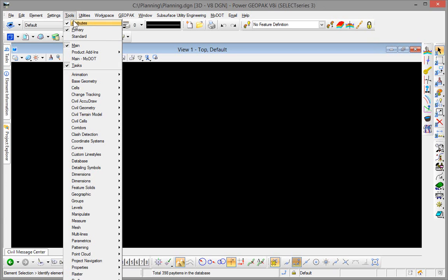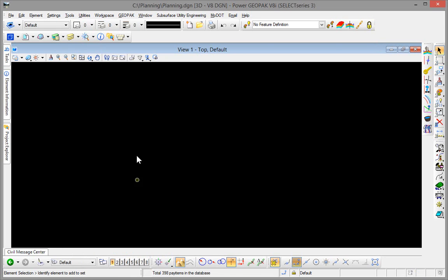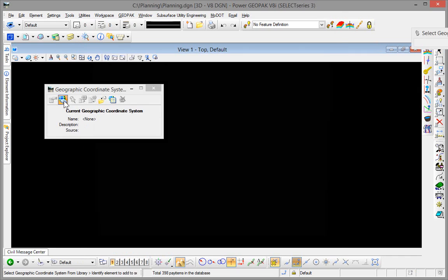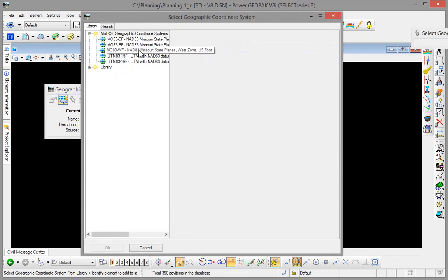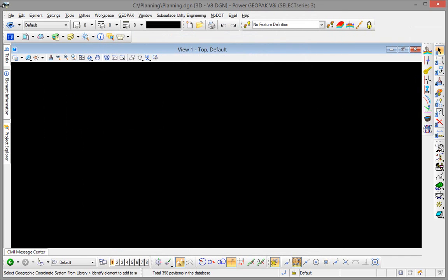With the new file created, we need to go ahead again and set our graphic coordinate system, just like we did before in the other file. So we use the NAD83 West Zone. Say OK, and then save those settings.